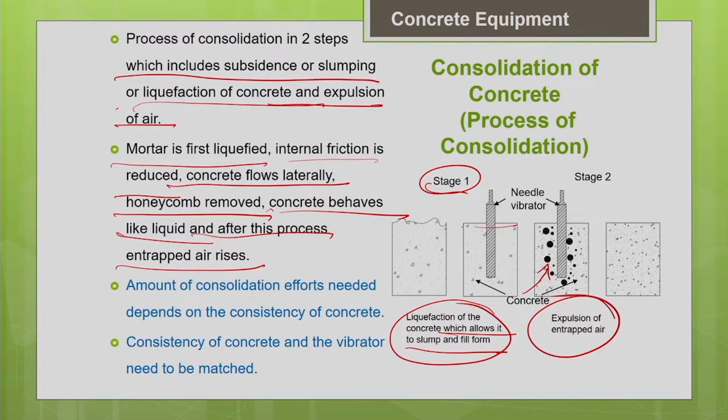As I told you earlier, how much consolidation effort you need basically depends upon the consistency of your concrete. For a very stiff mix, you need more consolidation because there are more chances of air entrapment. So the consistency of the concrete and the vibrator need to be matched.